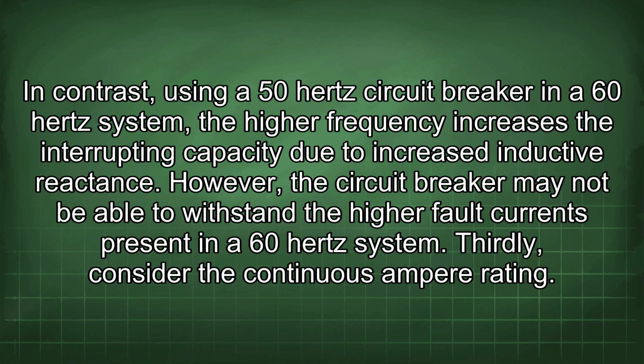In contrast, using a 50 Hz circuit breaker in a 60 Hz system, the higher frequency increases the interrupting capacity due to increased inductive reactance. However, the circuit breaker may not be able to withstand the higher fault currents present in a 60 Hz system.